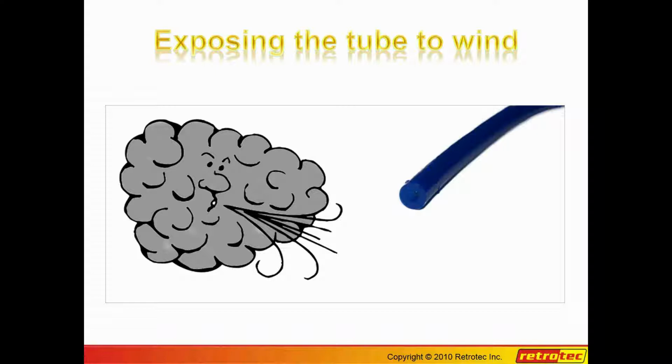tube outside. If I see more than a 1 or 2 pascal fluctuation in the pressure, it's called the baseline, I'll put a T on the end of that, and I'll run 2 tubes on there that are roughly about 15 feet long, and I'll pick up pressure at 2 different points, hopefully still downwind, and a few feet away from the building.